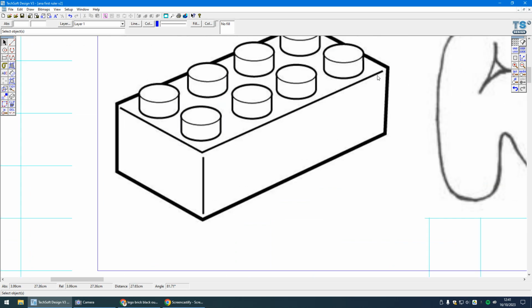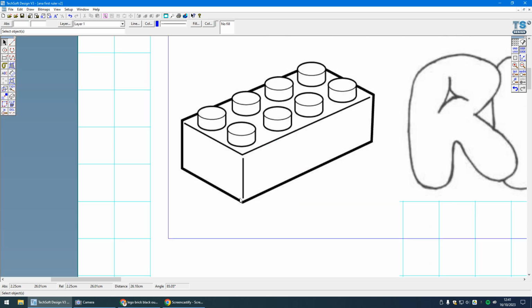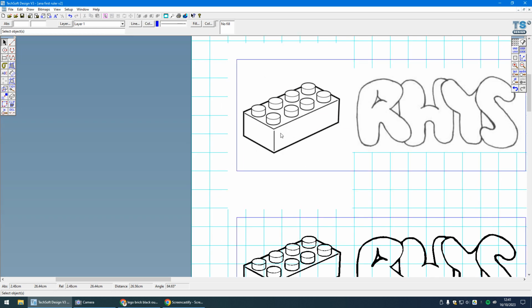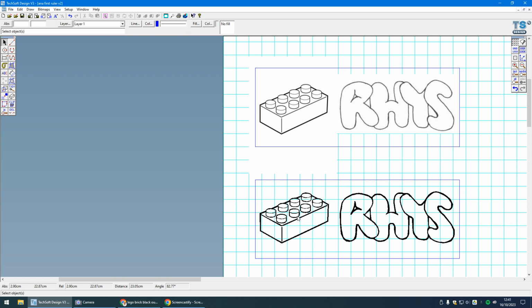Now be aware here that if I imported into my CAD file a slightly off black image, so it was slightly gray, again, nothing would be laser engraved. It's got to be solid black bitmap here for this to actually work. So it will engrave bitmaps if they are solid black. But what I've done down here is I've made it so that they are both vectors. So I'm making sure that whatever happens, we've definitely got solid black fills here, so they will definitely engrave.